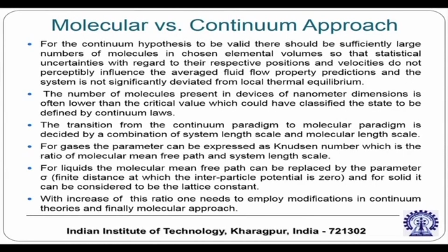Then the transition from the continuum paradigm to the molecular paradigm is decided by a combination of the system length scale and the molecular length scale. For gases, the parameter is very easily expressed in terms of the Knudsen number. For liquids, molecular mean free path is not a very meaningful parameter.